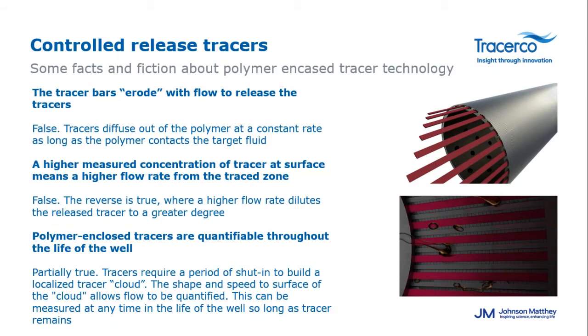3, polymer enclosed tracers are quantifiable through the lifetime of the well. This is particularly true. Tracers require a period of shut-in to build a localized tracer cloud. The shape and speed of the surface of the cloud allows flow to be quantified. This can be measured at any time in the life of the well, so long as tracers remain.